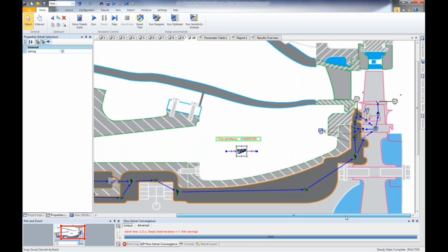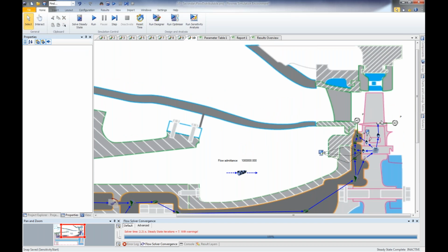I just don't think I understand what exactly it is you're trying to model at that point. Maybe if you can explain to me, I could answer your question more confidently. Okay, so what I mean is just upstream of the rotor near the hub, there will be some hot gases ingressing inside the cavity. Which ingressing? Yes, it will heat up the gas and eventually the disk surface as well. So how can one do that through scripting? Because it's not just defining the losses for a given element or resistance using script, but it's the interaction of different flow paths. It's a little complicated scripting.